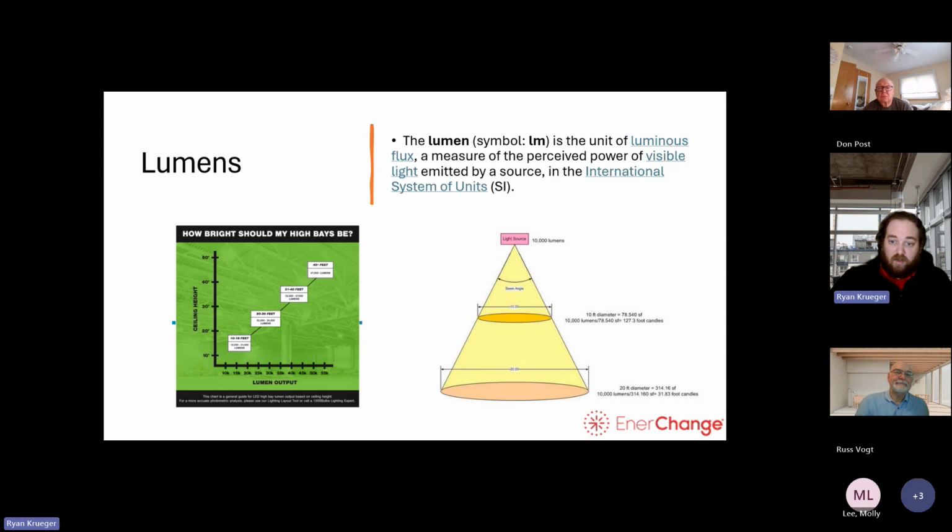But in this application, you're realistically looking at a fixture that's mounted 20 feet in the air. Once that fixture's that high in the ceiling, at 10 feet, it's way too much lumens. But at the floor, you're at 30-foot candles, which is realistically perfect for the application you're working with. And on fixture spec sheets, it generally tells you what the lumens are.